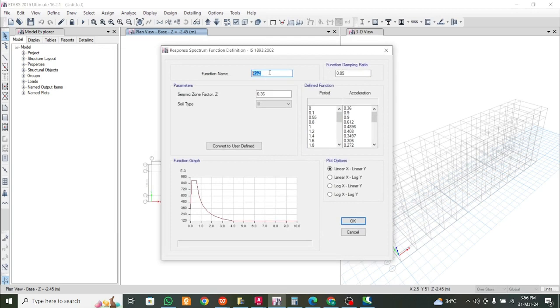So that's why we have to add this manually, and we have to use a separate table for that. Edit the table manually. So RSZ, or let's call it SLZ, that will be better. SLZ or SL vertical, or SLV will be better. SL, seismic load in the vertical direction, to be short.